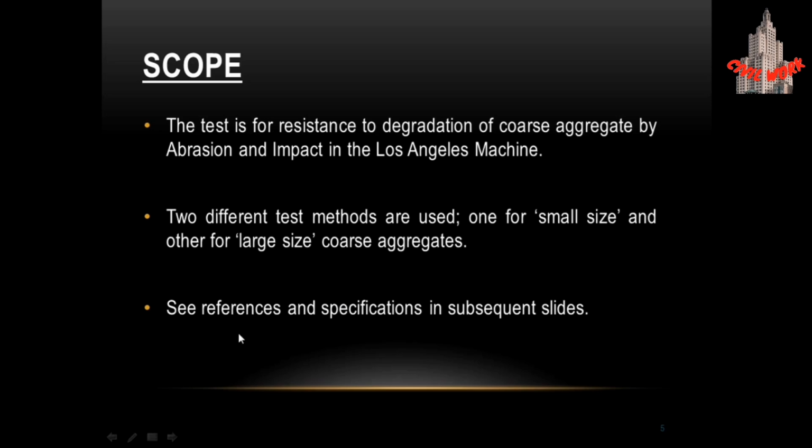We have references and specifications in subsequent slides. We have standards as ASTM C131 for the small size aggregates and ASTM C535 for large size aggregates.